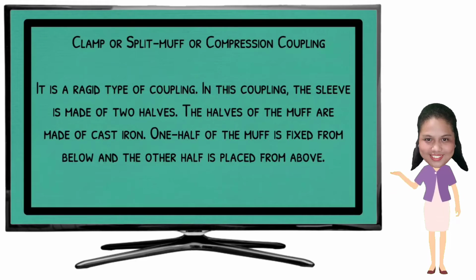The muff has a semi-cylindrical form that fits over the shaft. Threaded holes are supplied on the muff to allow steel bolts or studs to be used to connect the shaft. This connection is unique because it may be installed and dismantled without affecting the position of the shaft.